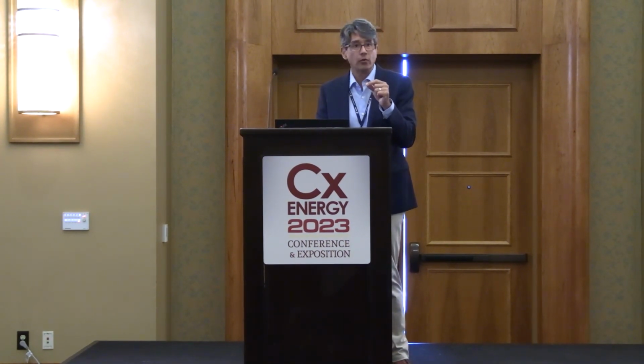And it could even mean that we're going to drill a unit out and put a bunch of holes in that unit. Do we really want to do that to get a temperature traverse at the entering side and leaving side of the cooling coil? Do we want to do that to that piece of equipment? Is it really critical that we have that kind of data on that unit in that certain situation? If it is, yeah, let's get it done.